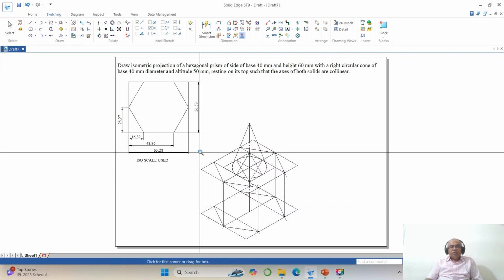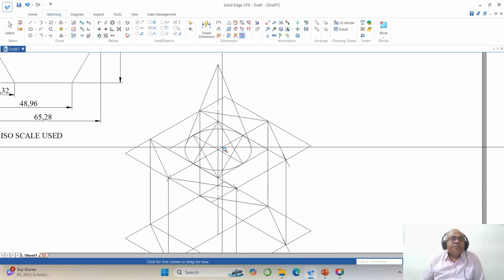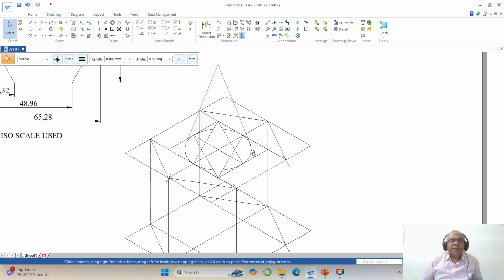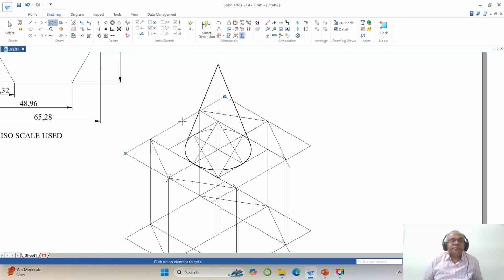then you want to take the things. So now you go to split this arc till here, then you split this arc till here. Now you go to shift by holding the shift key, select this line, this and this arc and this arc, make it 0.5, okay. Now you split this arc till here, then you split this arc till here, then you split this arc till here, this one